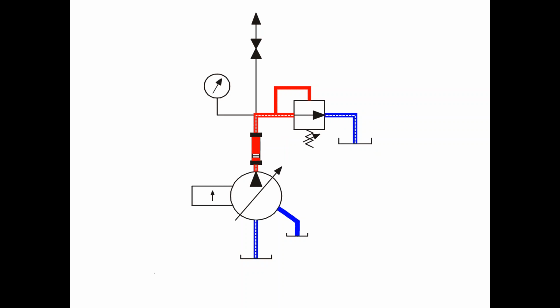This few $100s will pay for itself very quickly and reduce downtime because you can make this check in under 1 minute if the flow meter is already installed. So if you think you might have a bad pump, valve it off, run it through the relief valve, turn it down very low, see how much flow you get, then compare that to what you get when it's turned up very high. You'll know in no time.